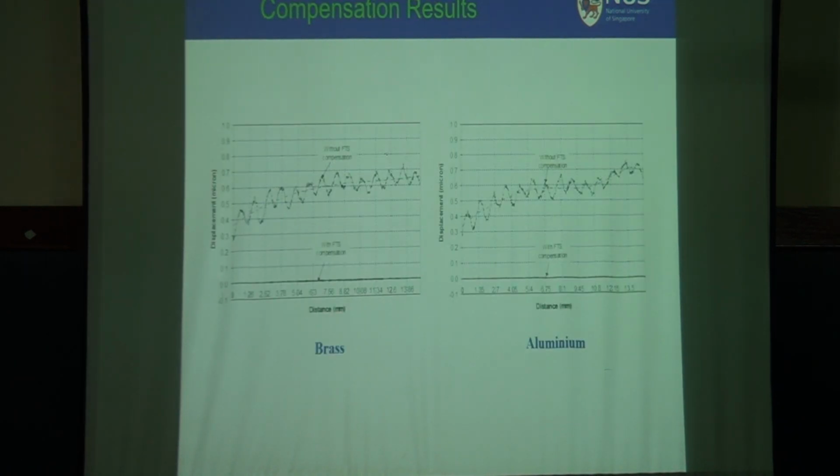You see, this is the result, this surface roughness, when we apply the feedback control, and the error is almost zero. Right? So this is the beauty, using fast tool servo, controlling both form error and roughness error, and you can get the best accuracy. You can bring it to nano accuracy.